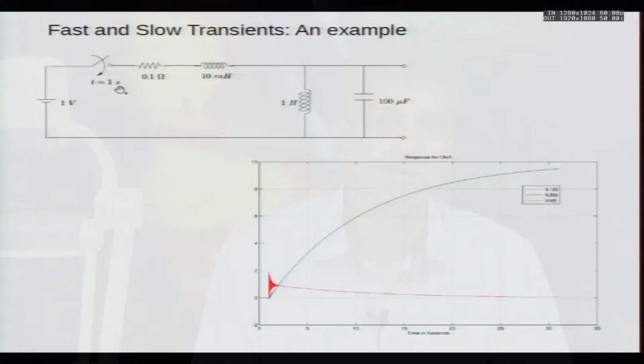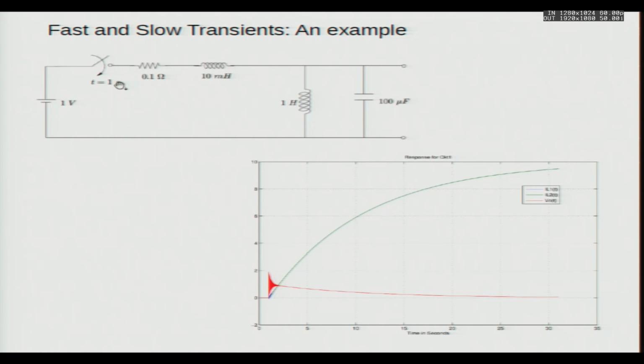So, if you go to this circuit which is shown here again, suppose I give a step change to this. Now, one interesting thing is, because in this circuit the natural response consists of a damped sinusoid which has a large negative real part, that is the rate of damping of that oscillation is very fast, and also the oscillation frequency is quite high.